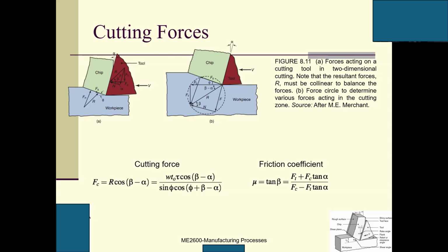You agree? Okay, great. So for this case, we will have Fn on this shear plane, the normal force. Fn is the normal force, and Fs is the shear force. If you want to remove this chip, remove this layer from the body of the raw material, you have got to apply this Fn, this Fs.